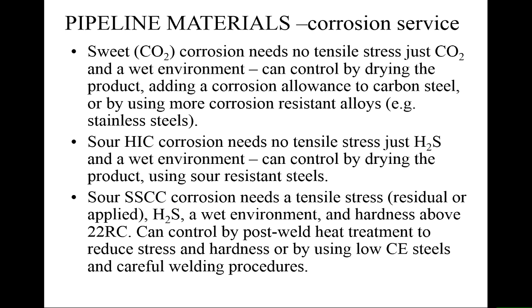The reason that I say welds here is, if you imagine a weld between two pieces of pipe, the pipes are cold, the metal that you're depositing is hot, it will contract as it cools down to room temperature, and it will pull against the pipes. So most welds are in a state of tensile stress, which can be very, very high. It can be almost up to, or exceeding in some cases, the yield stress of the metal.